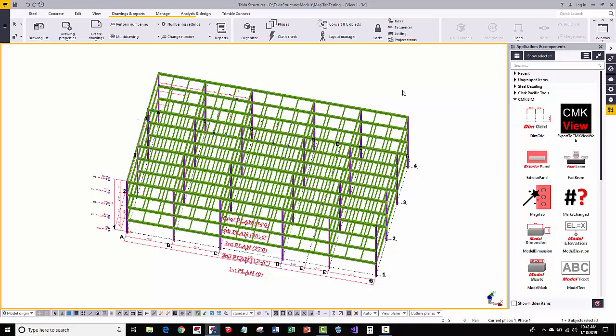Now in this video we're going to expand to showing end elevations as an individual mark versus it being inside of the part mark on the parts like we saw in the previous training video. So this is great if you're just quickly checking columns or sloped roofs, or if you have a floor elevation change and you want to quickly get the elevation value and note that in the model. You can use this tool to do that.